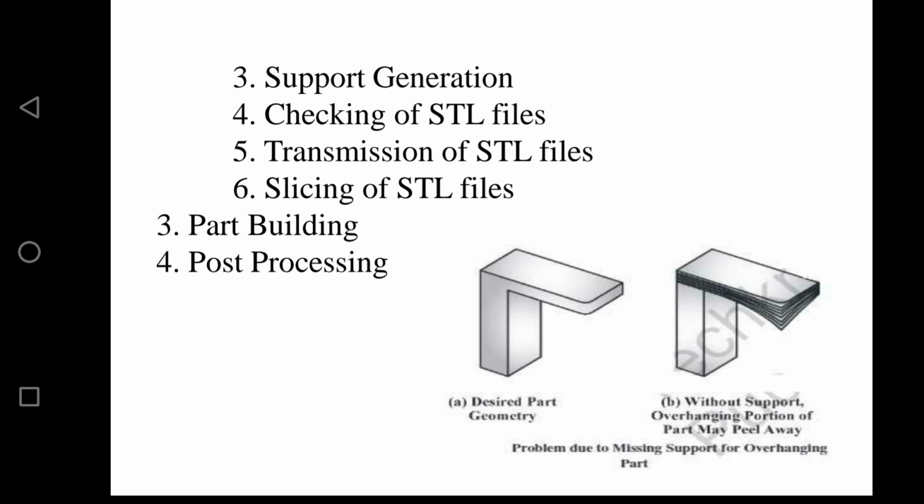Okay, so the sliced STL model is saved into new file formats like SLC, stereolithography contour, or it will be saved as a stereolithography model also, no worries in that one. And the data which we get after slicing the object is ready for use by the rapid prototyping machine. So this completes your pre-processing step.